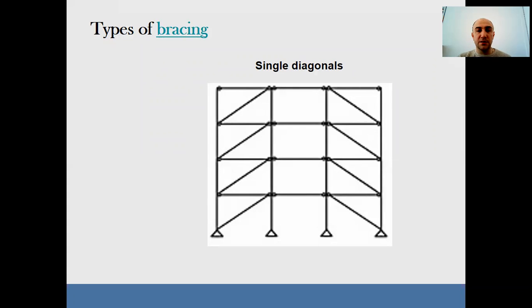The next one is diagonal bracing. Bracing or triangulation is formed by diagonal structural members in rectangular areas of the structural frame, helping to stabilize the frame. If a single brace is used, it must be sufficient for both tension and compression.